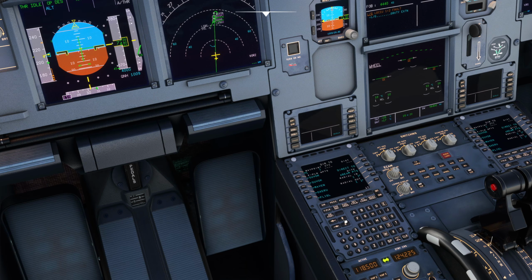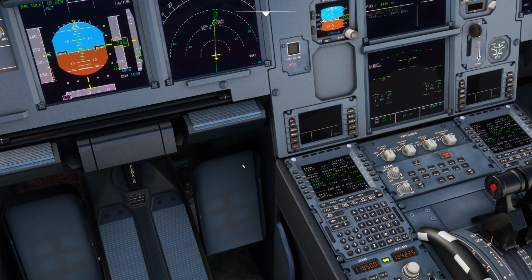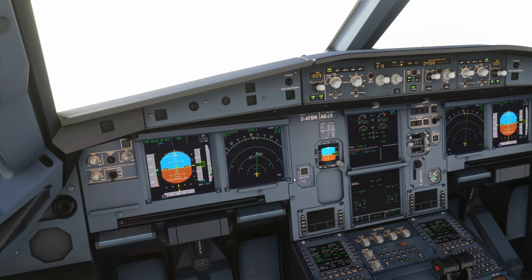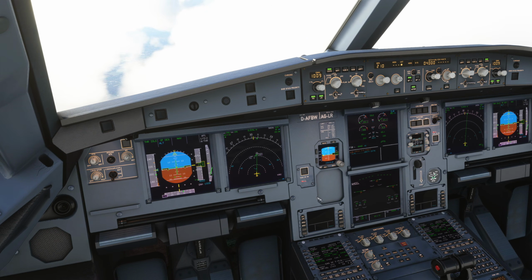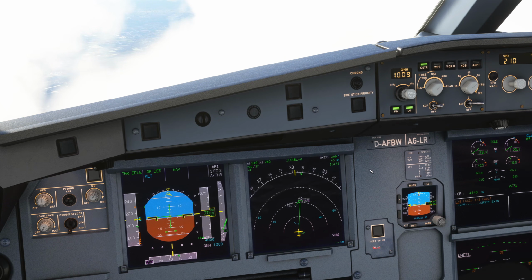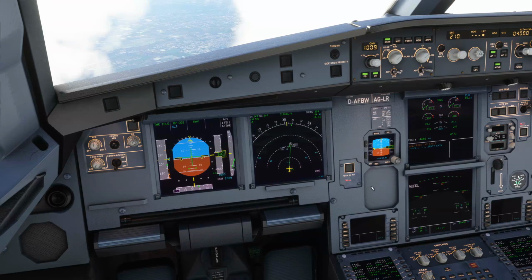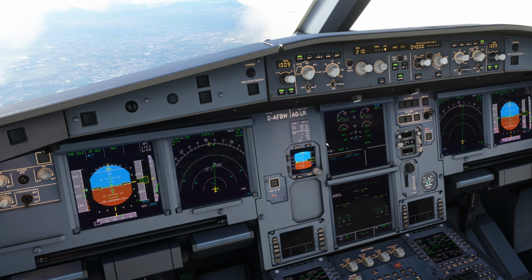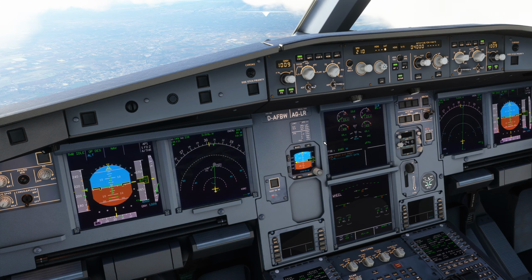Now this isn't a particularly shocking thing to do. This is just us arriving at an airport and flying an ILS, and lowering the landing gear. So you might think, well, we don't need to declare a Mayday. But then you're going to think, well, what if we don't declare a PAN, but then air traffic control carry on using the runway like normal, and somebody in front takes a bit too long to vacate the runway, and then you have to go around, and you've already lowered your landing gear. You've got a huge performance penalty, which in some circumstances may be very unsafe if you've got terrain on the other end. Luckily, we don't today. And you've got the issue of your fuel burn. You're going to burn almost 3 times the fuel you would have done as you head round and back in.